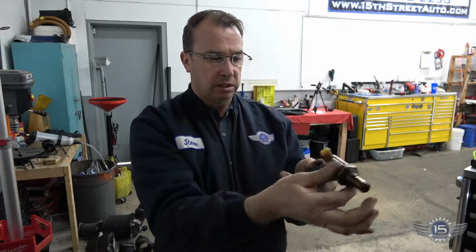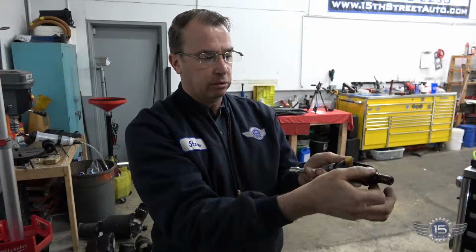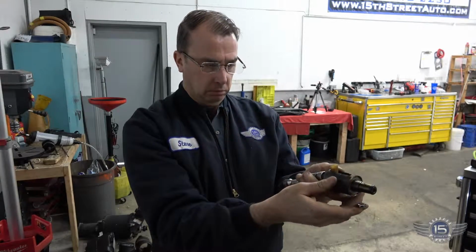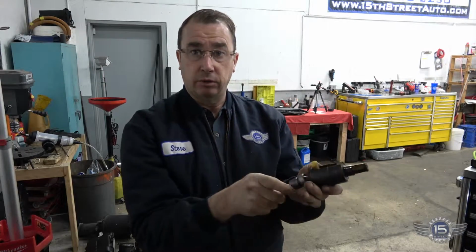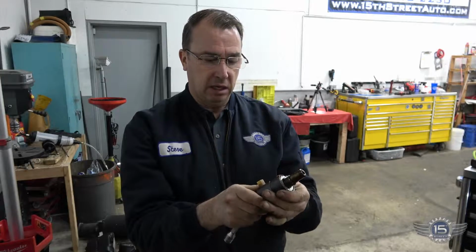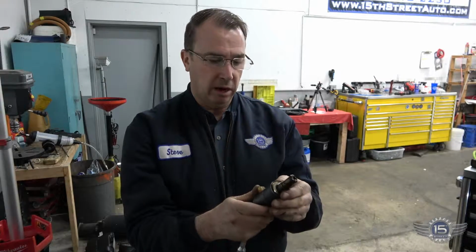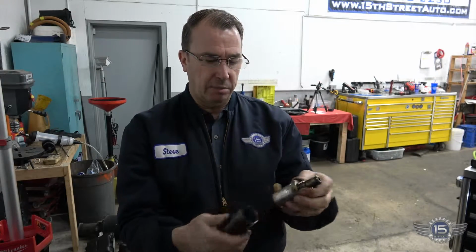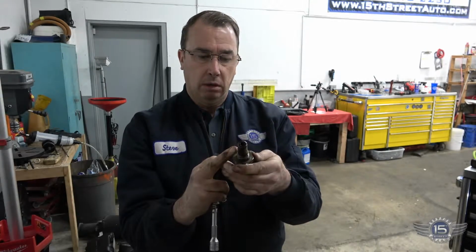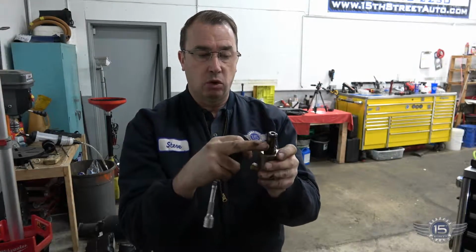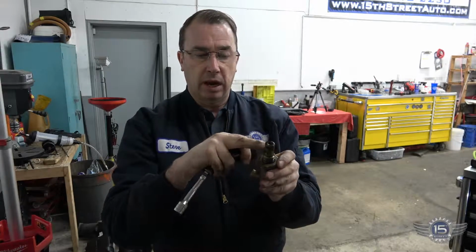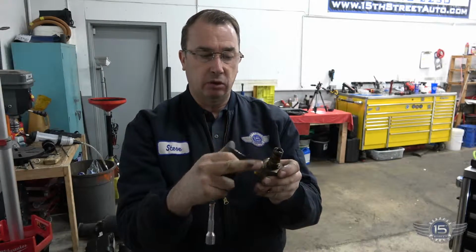And the way it works is this slides on, makes room for the electrical connector, so you don't damage that electrical connector when you pull it off. So without this, it's next to impossible to get out. But as you can see, the IPR is shaped just like that tool I have. Basically, that tool just bypasses. These holes in here are how the IPR regulates oil pressure. The tool's solid, so that's how that works.